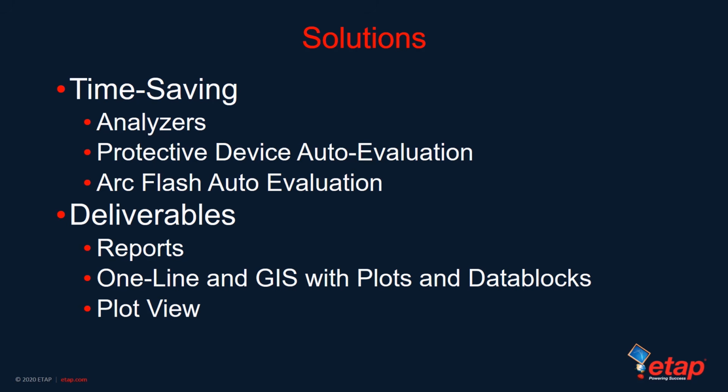Rulebooks are applied to automatically evaluate studies such as protection and coordination, as well as ArcFlash. We will be going over the ArcFlash auto evaluation solution and discover how much faster it is to evaluate incident energy limits during the protection and coordination phase of the project. We will also discover how using PlotView provides a plot interface that is not just a final deliverable, but a method to evaluate results as studies are performed.